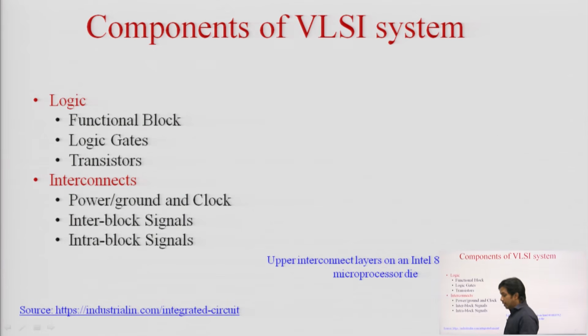Before the 1990s, the importance of interconnect was not that much, because we were only concentrating on the delay of the gate because of low frequency and lower operating or computation devices. But as the density of the transistor is increasing, more interconnect is also required to connect those transistors. Therefore, we have to take care of the importance of both the gate delay and the interconnect delay, both should be taken care of.